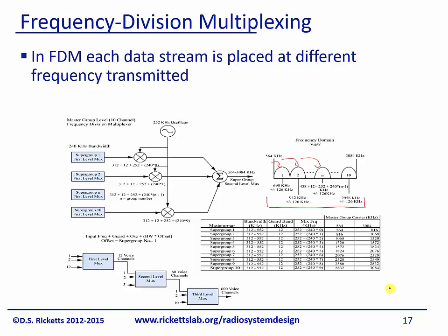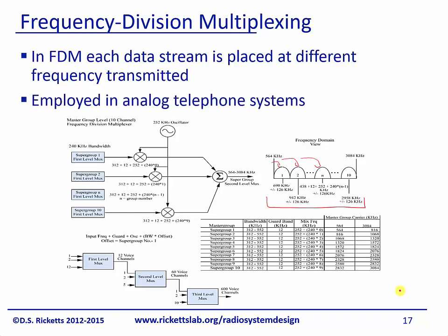In addition, because you can transmit at different colors, different wavelengths, you can actually stack a bunch of high-speed on-off key communication standards right on top of one another. So fiber up until recently and even now still is really not a bottleneck. We can pretty much put as much data as we need across it. And if we need more, we can just start to do what radios have done for the past 50 years, and that's start to adopt more advanced transmitter architectures such as QAM and PSK that we've studied before. And here's an example that in the old analog telephone system, frequency division multiplexing was something that could be done.